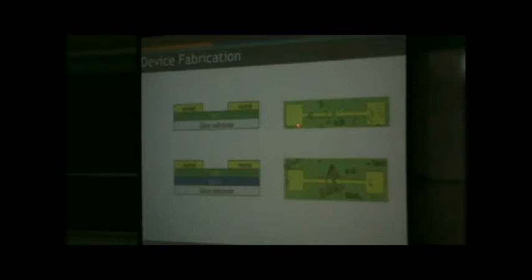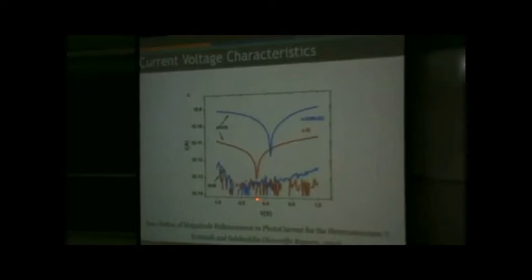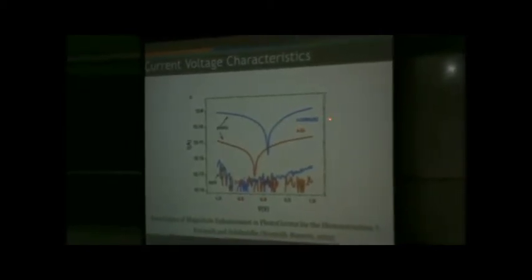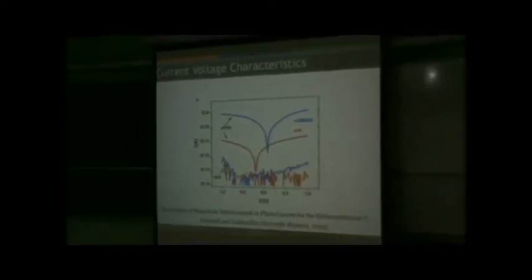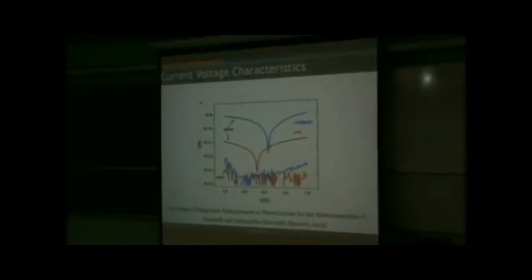We just put amorphous silicon, we just layer transfer MoS2 on top, and we look at the dark current and the photocurrent. And you see that dark current is the same for just an amorphous silicon photodetector and an amorphous silicon MoS2 heterostructure photodetector. But the photocurrent is almost 2 orders of magnitude higher. For the heterostructure, I get almost 2 orders of magnitude higher current, and this is what we expected because I'm creating a PN junction. Okay, so the junction increases the sensitivity.